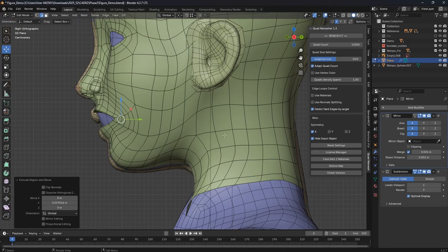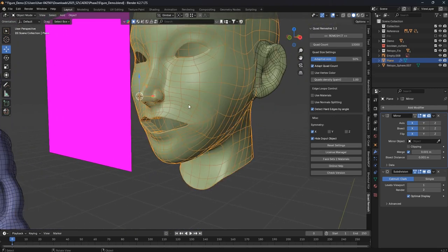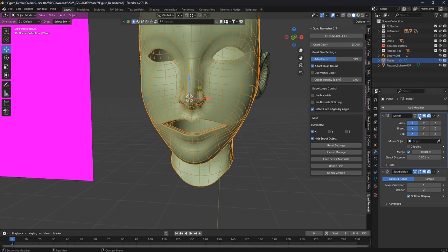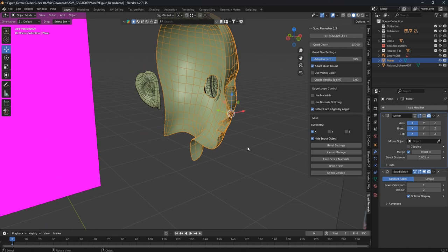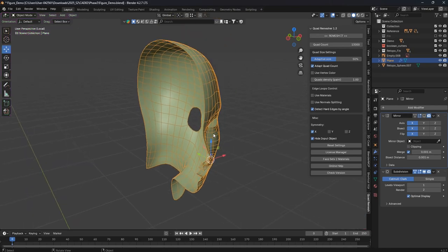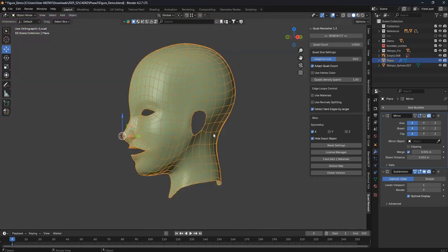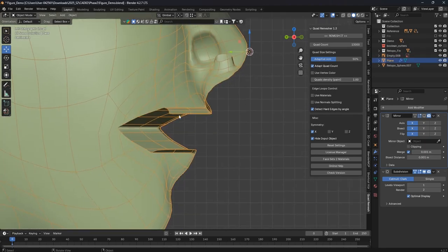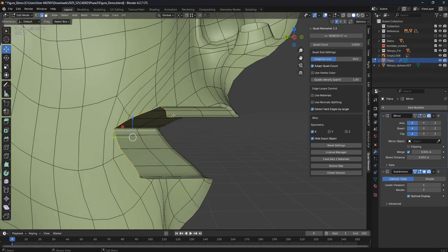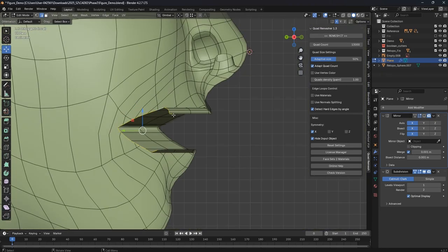And how about the side view? For now, I want to temporarily turn off the mirror modifier, and I'll probably just see this side. It will be fine. So let's choose this side. Let's use the slash key to turn off the other things. Go to the side view and choose the edge that we already have. Okay, let's keep extruding. Let's press E for extruding.